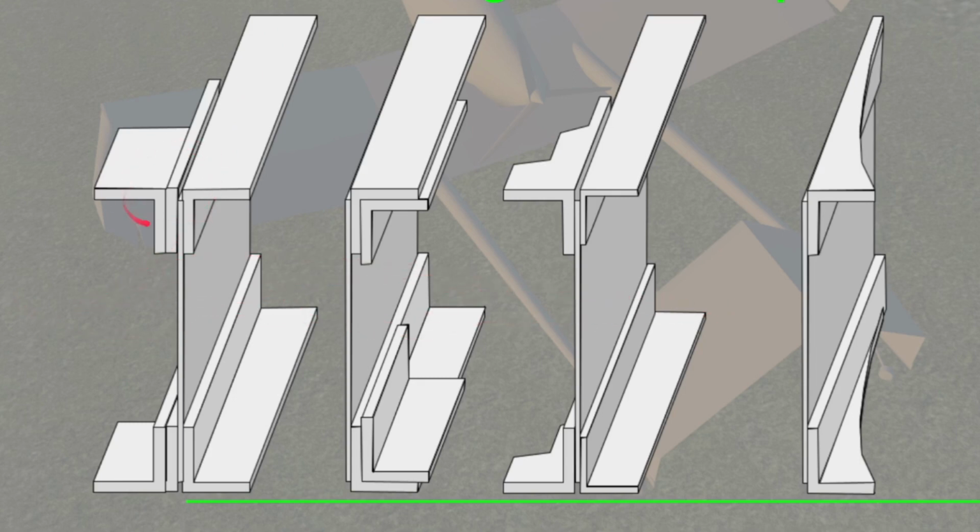So this up here would be a spar cap. This down here would be a spar cap. This vertical in here would be the web. So your spar caps handle the compression and tension forces, and your shear web is going to handle, as the name implies, the shear forces. We'll talk a little bit more about what shear is here in a minute. But here's some possible examples of how to construct a spar.